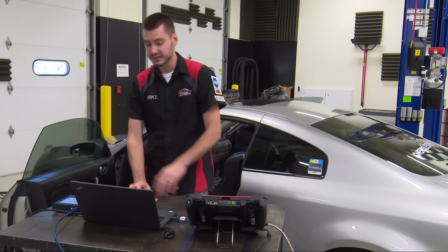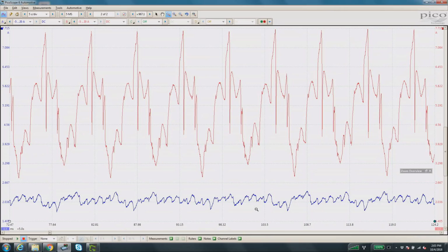And that's what we're seeing here with our blue trace. It looks pretty good. This is what we would be looking for with our blue trace for a known good condition. You look at that red trace, it is all over the place, right? We are seeing huge amperage swings. We are seeing a dirty, messy motor. It is not a good motor on here.